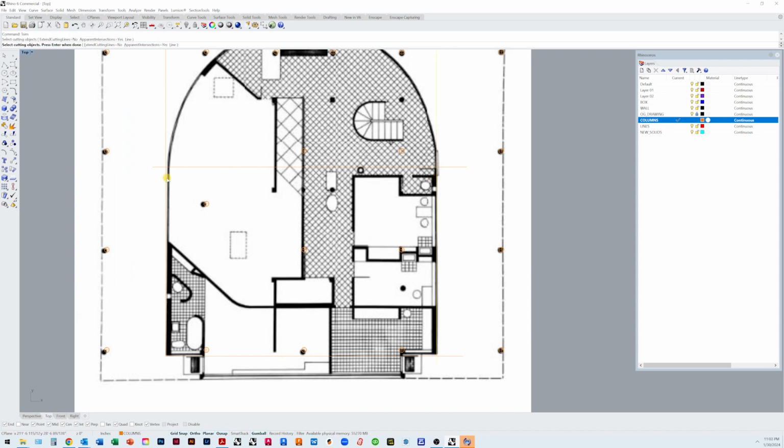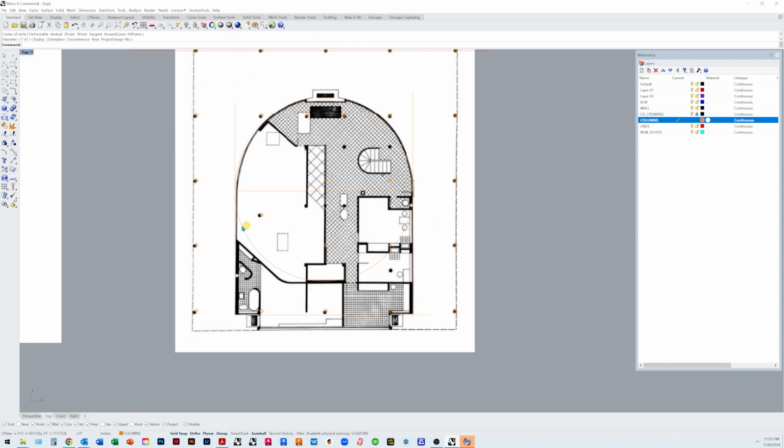Use these as cutting objects. Right click, trim these two. And then I'm going to try to draw a circle. So if I draw a circle, I pick the center of that line, then I click to the outer part of that line. Then I have a circle that pretty much matches with that. Then I'm going to click the end of this line as a trimming piece. Got half a circle here, trim here.